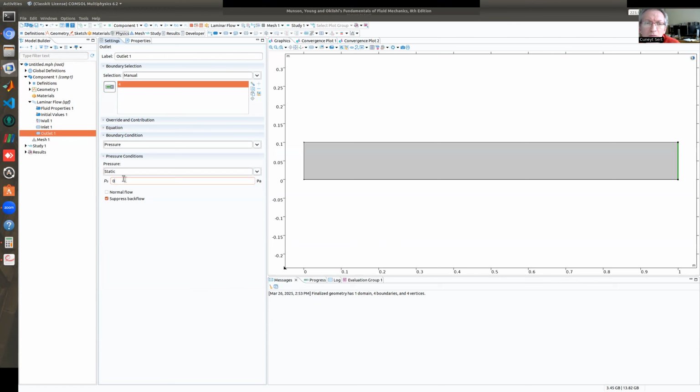So I was talking about pressure and in incompressible flows, only pressure variations, pressure gradients, how pressure changes in the x direction, how pressure changes in the y direction. In other words, dp dx, dp dy. Those are important, not the pressure values themselves. If you remember the governing equations, what are the equations that we are solving in this CFD simulation?